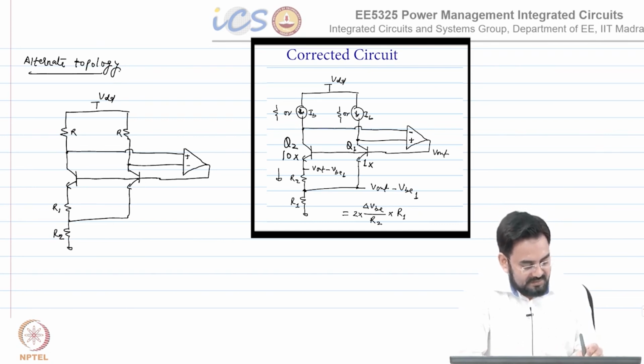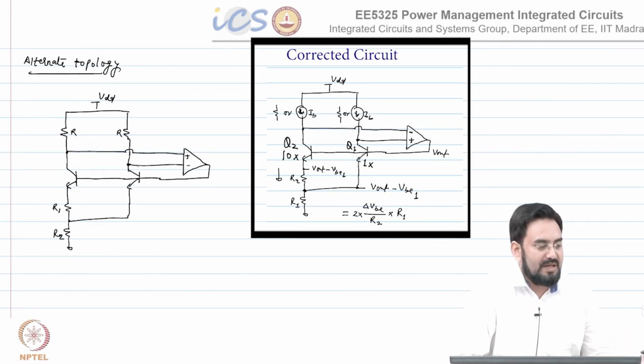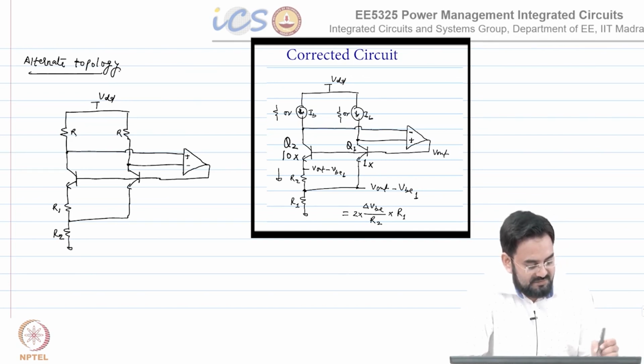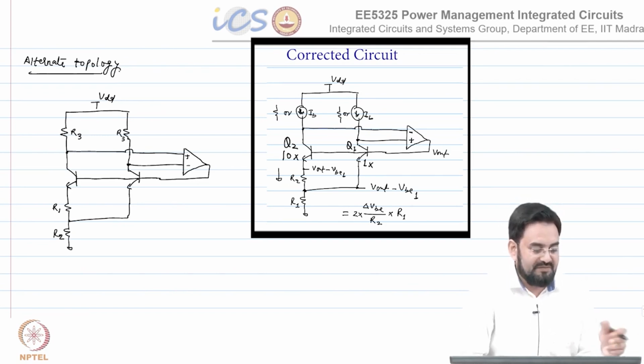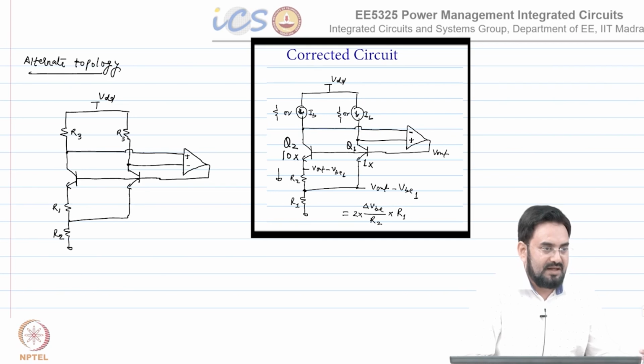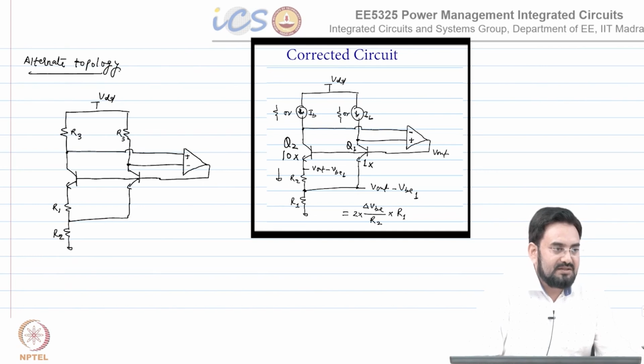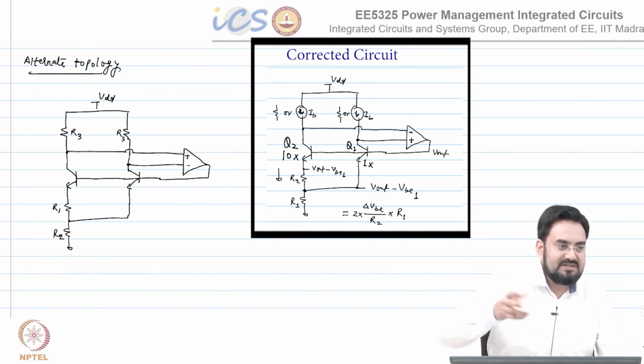Okay, again the same thing. So, this is an op amp with negative feedback. So, these two voltages will be the same. In order to have the same current in these two bipolars, you need these resistors to be the same. So, if I call it R3, this also should be R3, correct. If you have a different value, then the current will change, and in order to have delta VB equal to VT ln M, you have to make sure that you have the same current, so that the M factor is only coming from your reverse saturation current. Okay.